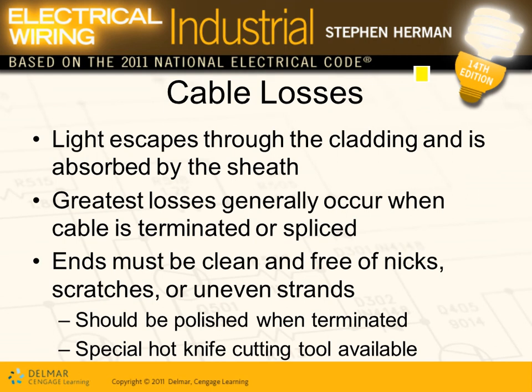Light escapes. There will be some light, guys, that instead of bouncing and going all the way to the destination, gets absorbed and escapes through the cladding. Absorbed and escaped through the cladding. So that's part of your losses. And the greatest loss, as everybody will tell you, goes through the termination and the splices.